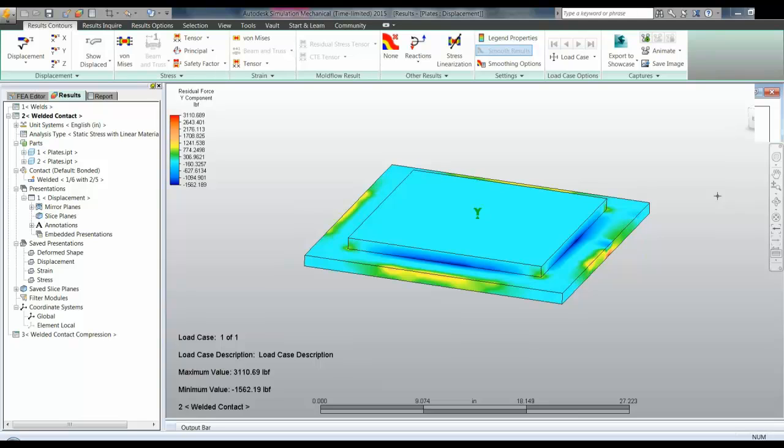Okay, so Boris had a question here about singularities. Is there a way to distinguish between real stress and singularity response? There is, and if I am under the belief that I perform a finite element analysis and I press all the buttons one time each, like mesh and analyze, and I see results and think that those results are complete and satisfactory, then I'm making a mistake. I'm only getting a small part of the picture.